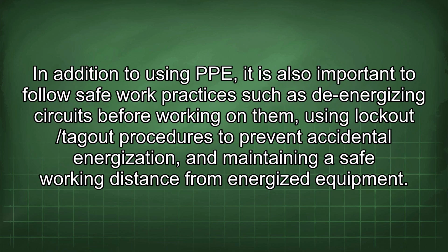In addition to using PPE, it is also important to follow safe work practices such as de-energizing circuits before working on them, using lockout/tagout procedures to prevent accidental energization, and maintaining a safe working distance from energized equipment.